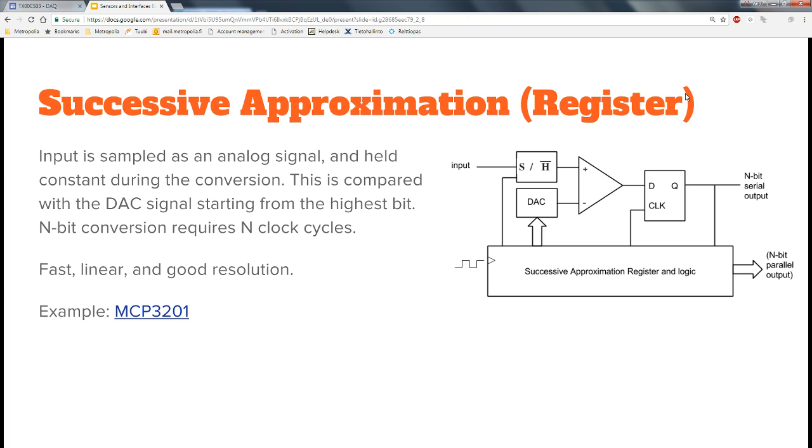If the signal was still lower, then you know, okay, you fix that highest bit and then try the next bit. If this actually was bigger than the input signal, then you would just know, okay, this bit is 0. Next you try the next bit. Leave the highest bit as it is, and then test the same for the second highest bit. Is it lower or higher, move to the next one. So basically, if you do 10 comparisons like that, you have 10 bits.